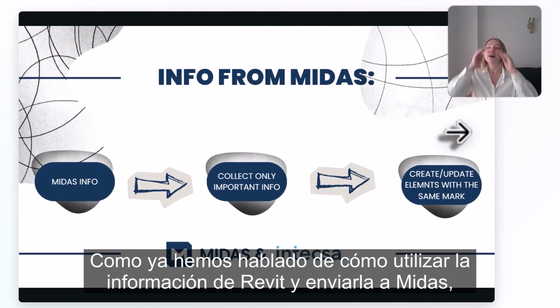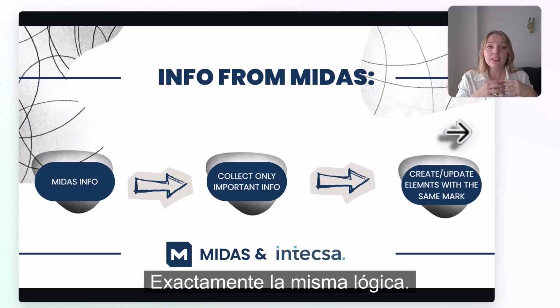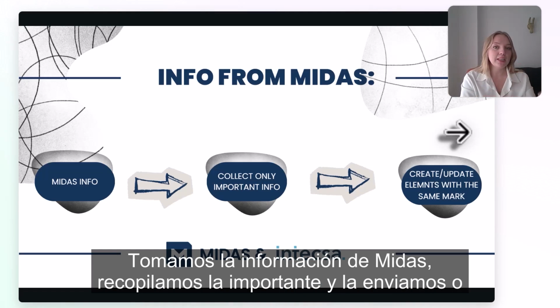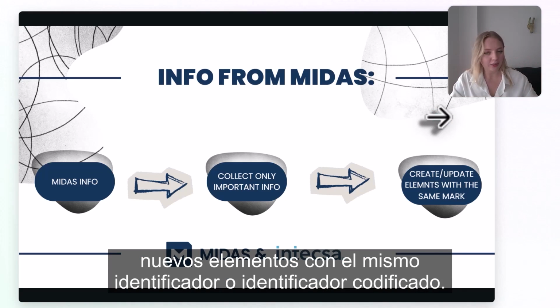All right. So as we talked already about how to use information from Revit and send it to MIDAS, let's now talk how to get information from MIDAS and send it to Revit. Absolutely the same logic. We take the MIDAS information, only collect the important one and send it to Revit to update or create new elements, maybe delete elements with the same identificator or encoded identificator as we discussed.